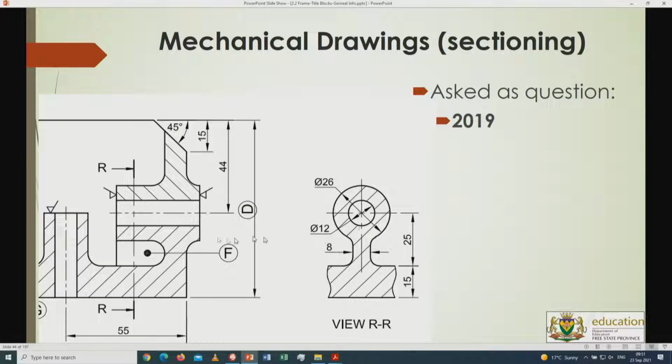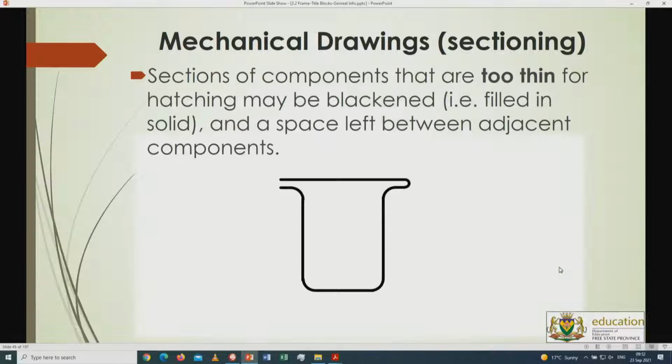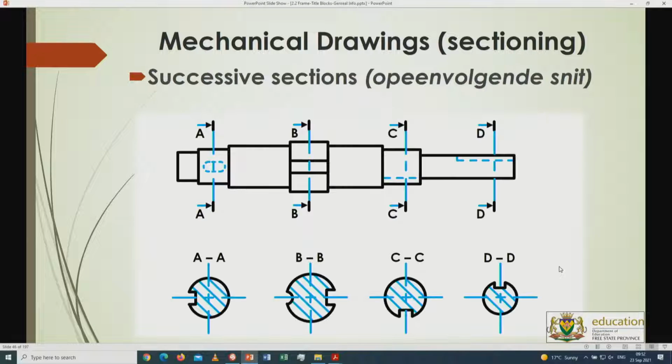All right, so there you can see no profile of the rest of the components. There are some other components, but nothing of that. It's just the profile of this area, no background information, and then that is when you get a removed section. If the profile of everything was over here, then it's a section drawing, but in this case, no background of the components over here, so that is giving you this option. All right, so too thin to hatch, so therefore it's just dark lines.